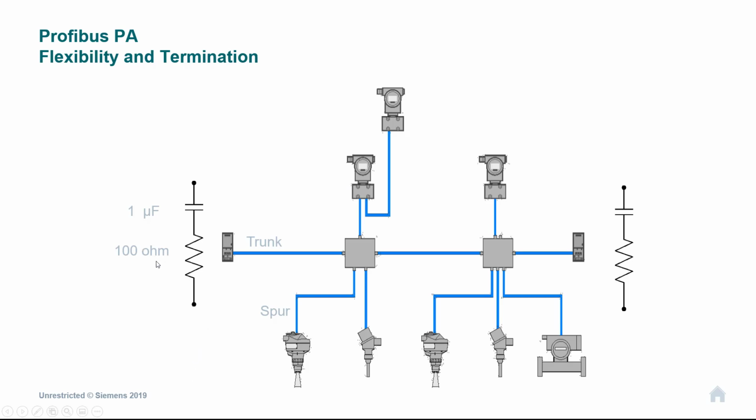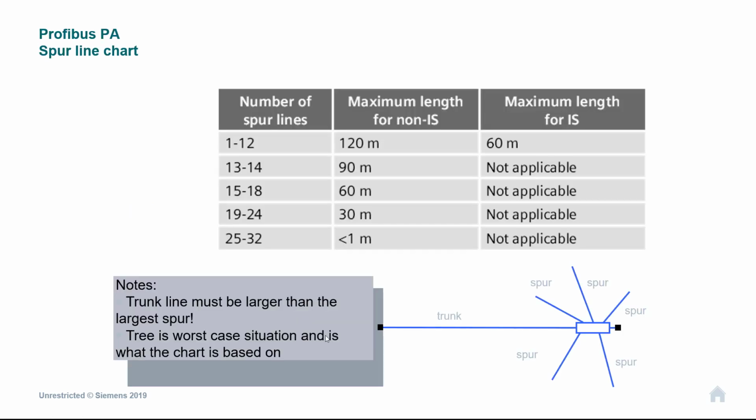So I have people ringing me up asking me about these resistance values and capacitance values for end-of-line terminators. Really, the message is go and buy a proper end-of-line terminator. Don't try and make your own, especially if you're working in hazardous areas.